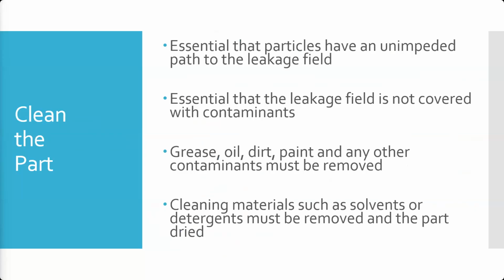Cleaning materials such as solvents or detergents, however, also have to be removed and dried beforehand. We don't want the cleaning solvent breaking down the carrier solution. Right? If we use alcohol to clean our part, our carrier solution is petroleum-based. You put a bunch of alcohol into a petroleum product, it's going to break it down. That's the whole point. We use alcohol to clean it, to get rid of oily stuff. And so things like that, we got to be careful.